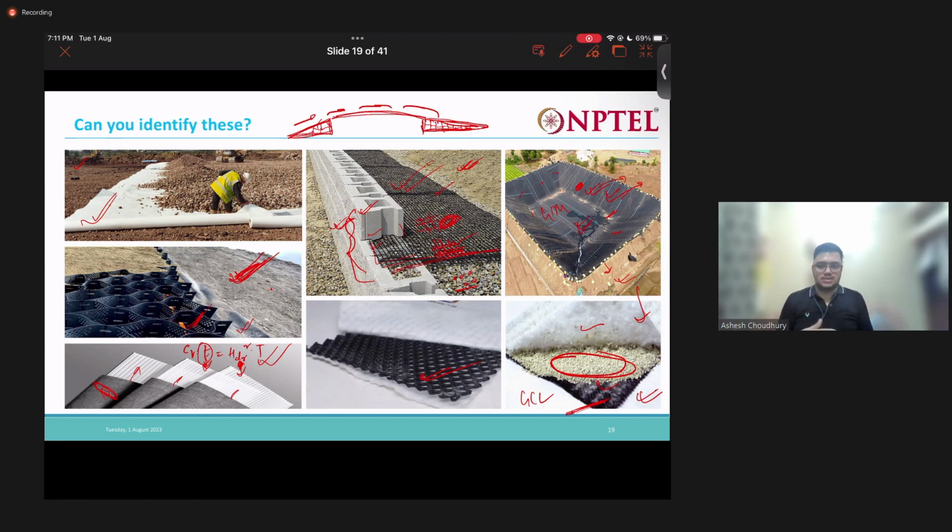The soil below was a little soft. The foundation soil, above which the reinforced earth structure of the approach was to be constructed, was a little soft soil. So PVDs were installed to accelerate the consolidation process, so that after the consolidation occurs in say 2 to 3 months, the reinforced earth structure can be built over it.